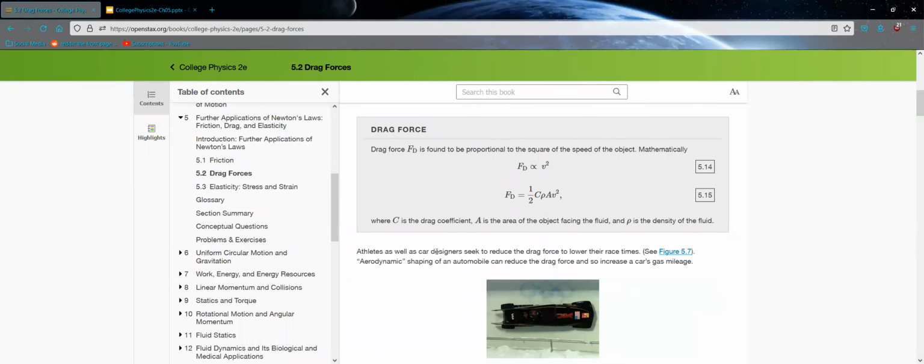Again, we're dealing with multiplication here, nothing too super difficult, but knowing your variables is important. So some of the variables involved with force include a drag coefficient, which is similar again to the mu coefficient for friction, same concept. The area of whatever you're dealing with, how much is being hit by the air, right? That's why sleek cars are very thin. The density of the fluid, again, a known product if you're flying through air versus water versus syrup, I guess, and how fast you're going, velocity squared, right?